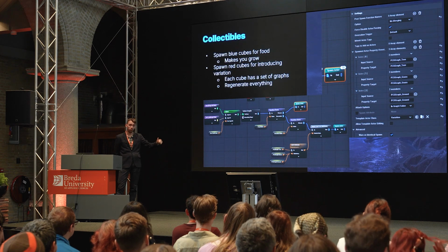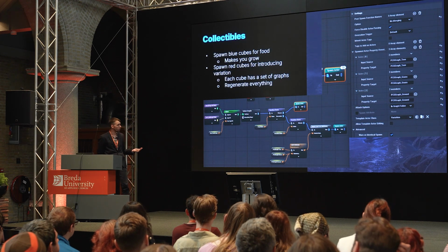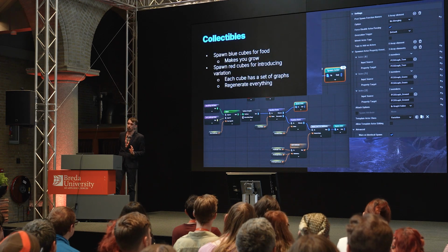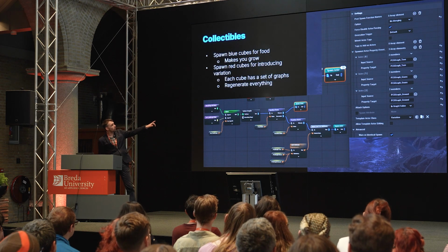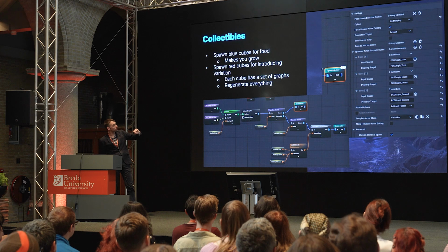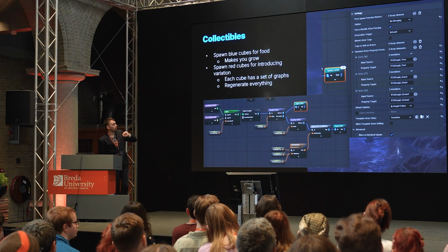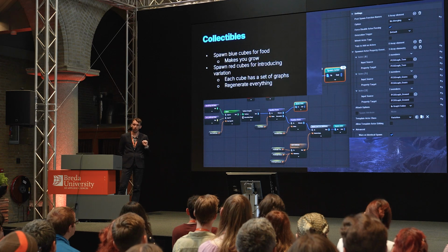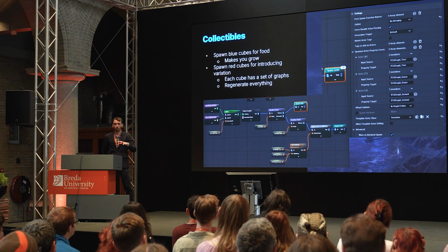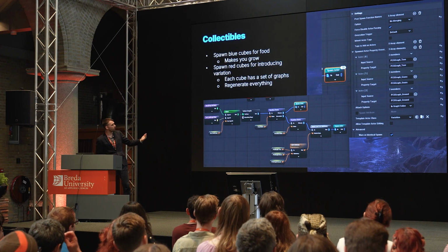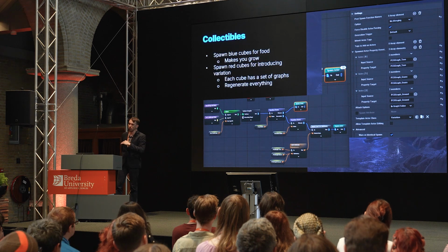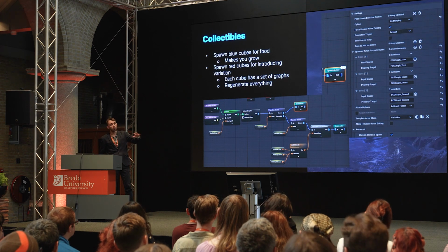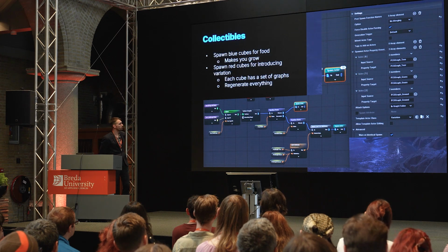So you have one graph for the trees, one graph for the grass, one graph for the ground. And those will be directly pushed to the blueprint that I'm going to spawn. On the spawn actor, you can see the spawn actor property overrides. I have 3 properties on my blueprint, and I will push the attributes from PCG to the actor directly. So that's another way of interaction between PCG and the rest of Unreal: you can send information from PCG to the actors.